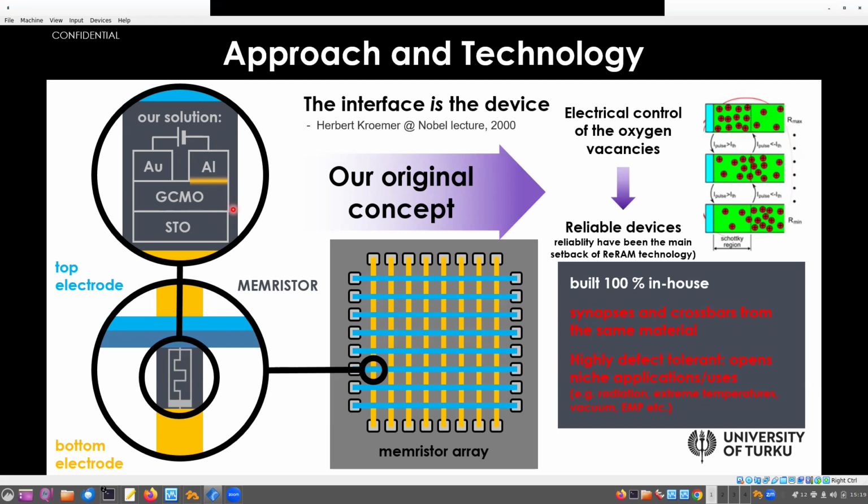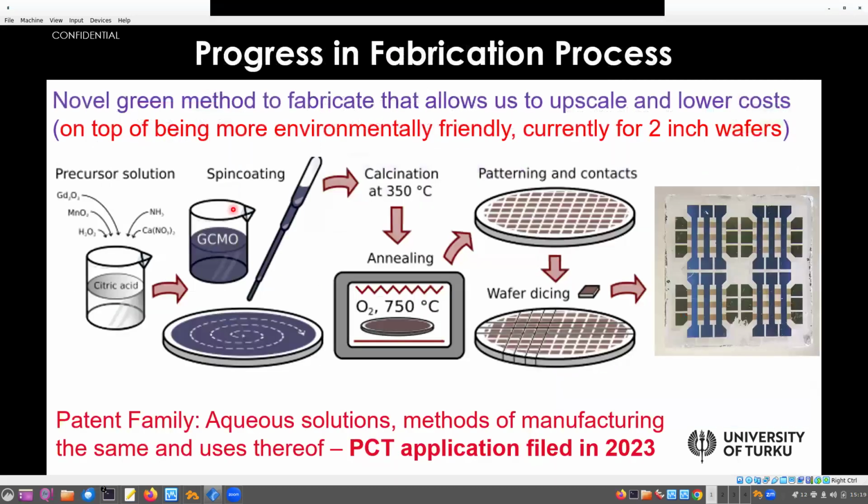The first things that we did were on single crystal strontium titanate. We are working on putting it on silicon. But we can do it on lanthanum aluminum oxide, which currently allows us to make 2-inch wafers. The pulsed laser deposition system we have in-house only allows for very small samples, so we can't do pulsed laser deposition on 4-inch wafers or something like that.